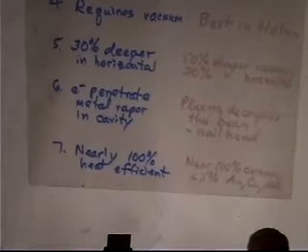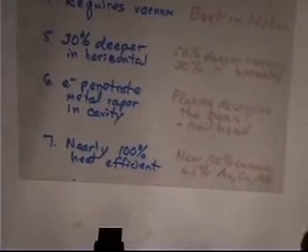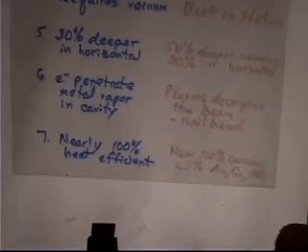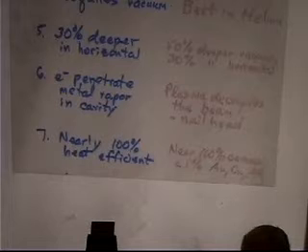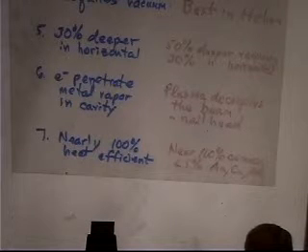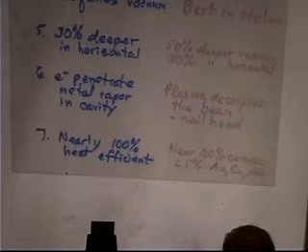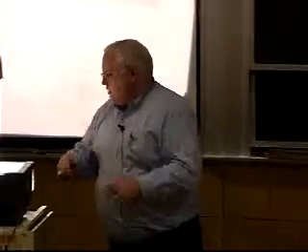Inside that cavity, there is more than 1 atmosphere of metal vapor. I'm vaporizing the metal, pushing the liquid out of the way and drilling a hole. That deep keyhole is going to be my weld pool shape when I'm all done.